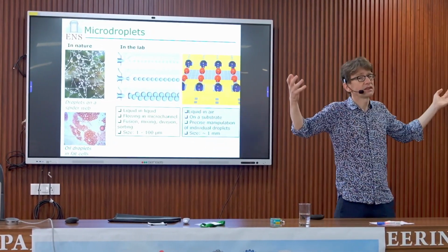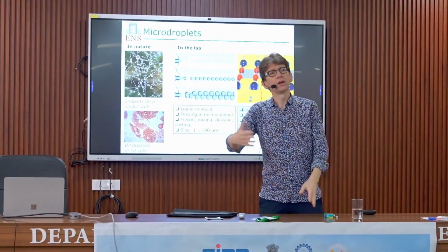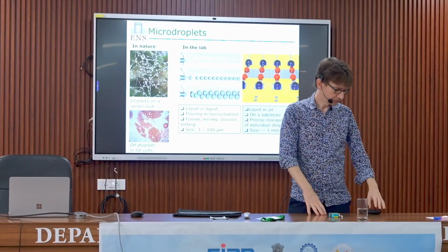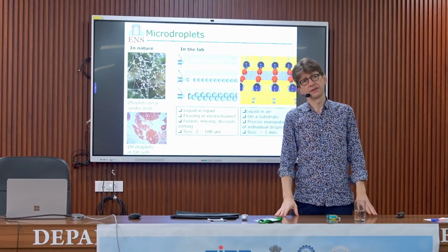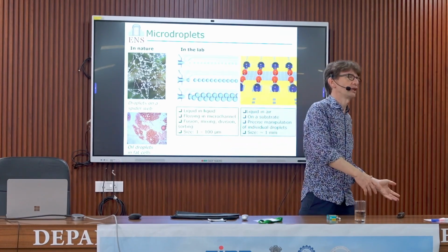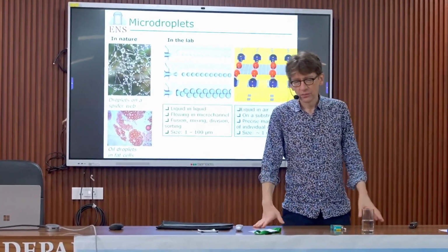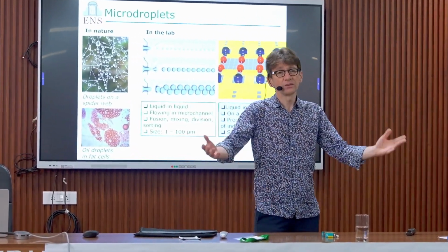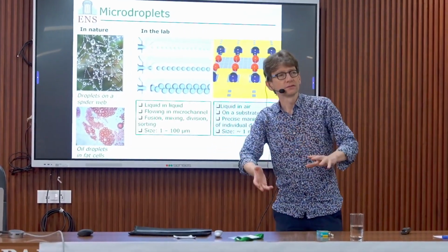We could think that, like we have the Reynolds number to know if it's a laminar or non-laminar regime, we could just compute the capillary number to know if we are in a jet regime or a droplet regime. The problem is that in microfluidics in general, you are in a channel.